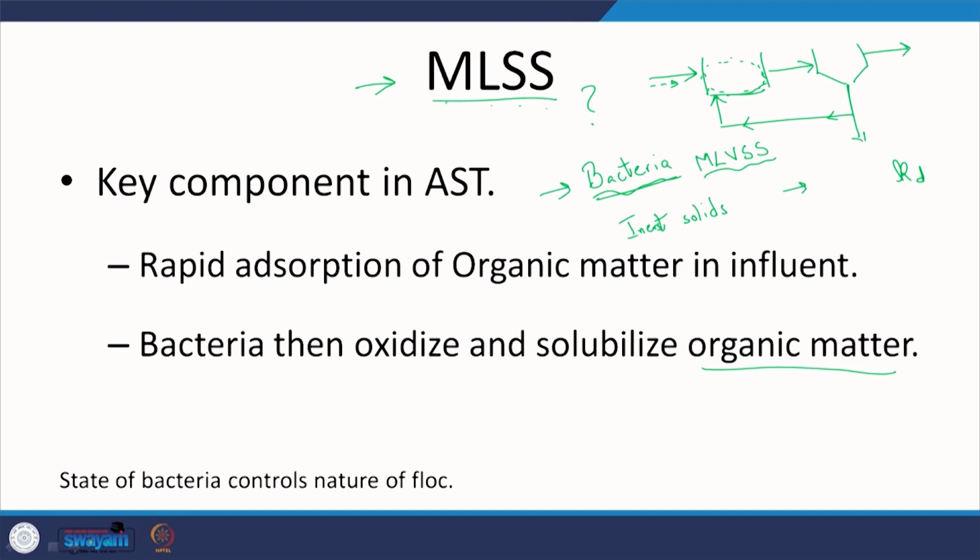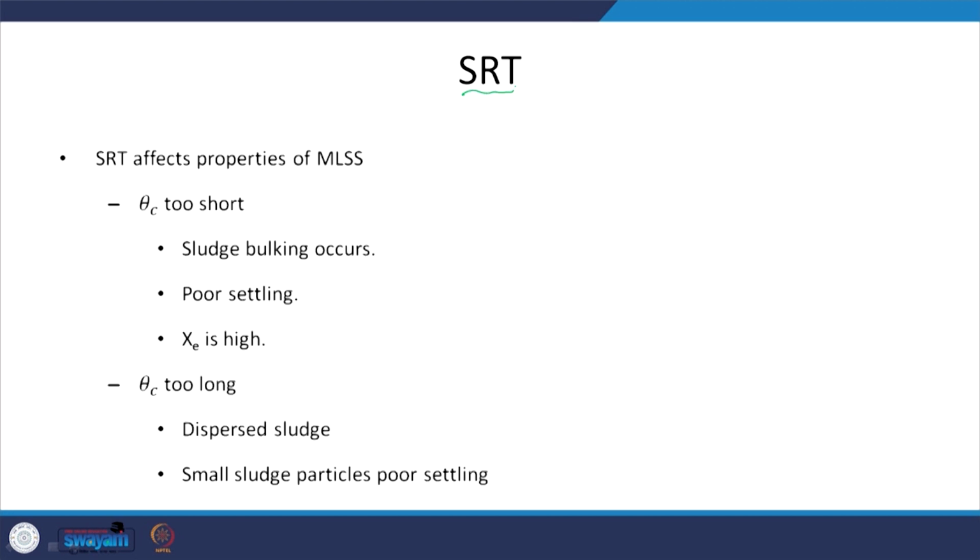So let's move on. Solid retention time: some aspects that we need to be aware of. First, this is not HRT. HRT is about hydraulic or water. This is about solids, and when we say solids, we are referring to the microbes. So SRT affects the properties of MLSS, obviously. Why is that? I have this tank and this is the recycle, right? So the recycle and the concentration will affect the time that my microbes spend in my system.